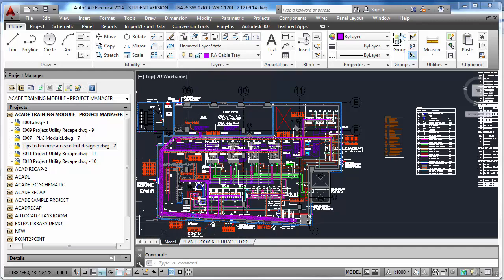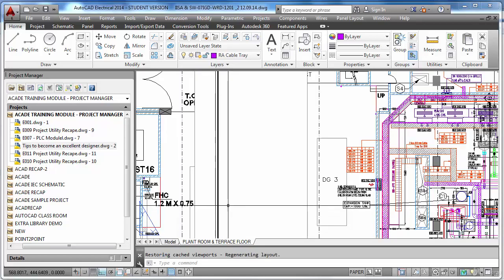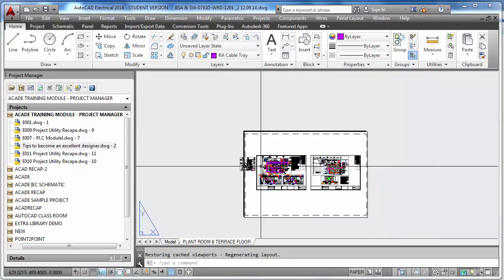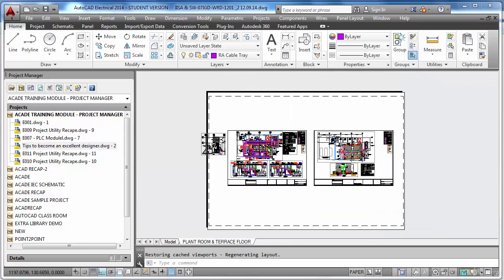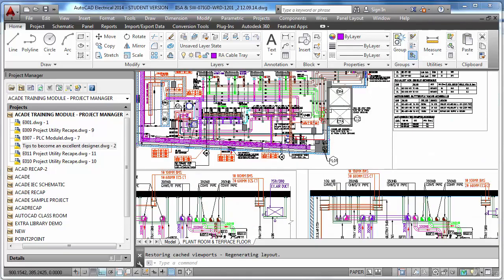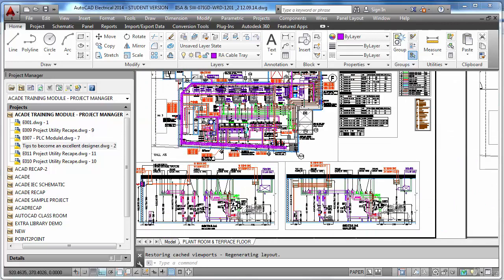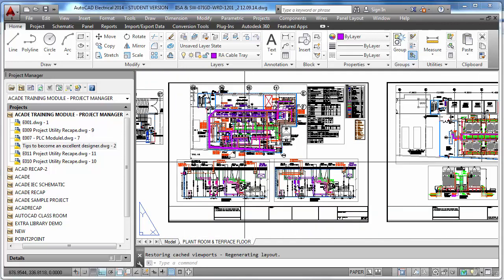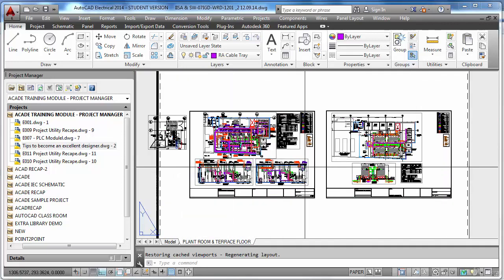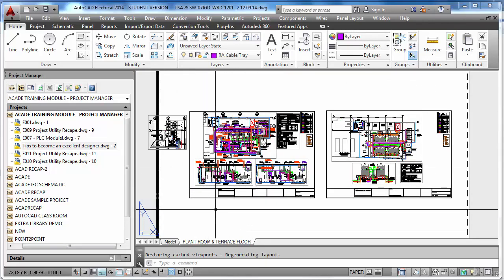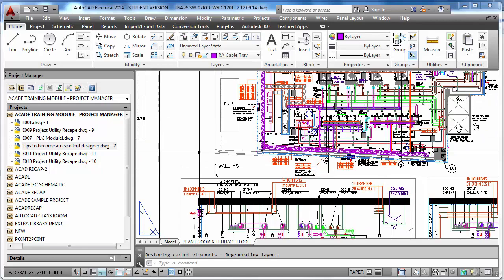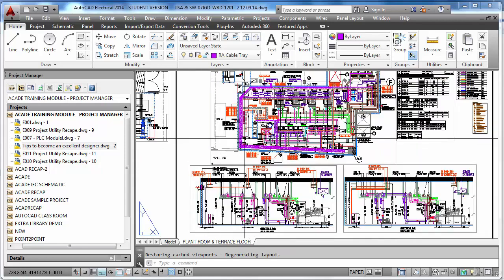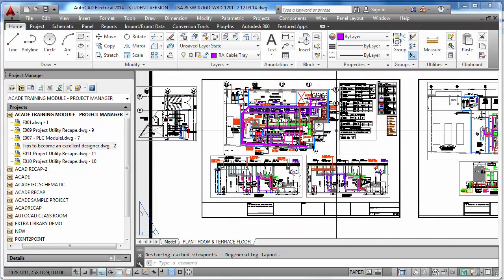See here again, this drawing is made in model space. If you go to this sheet here, you can see this in paper space. This is how many people draw, but never ever make two drawings in one sheet. This is not recommended, but here it is just like that. These are all made in paper space.